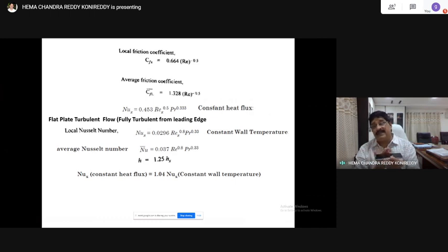There you don't know what the temperature of the solid is, but you know the heat released from the surface. Now in the constant heat flux case, we calculate T_f. What is film temperature? Film temperature is the average of the plate temperature and the ambient fluid temperature. So since wall temperature is not available, you can assume that fluid properties are taken at the film temperature. Okay, so that covers constant wall temperature and constant heat flux conditions.